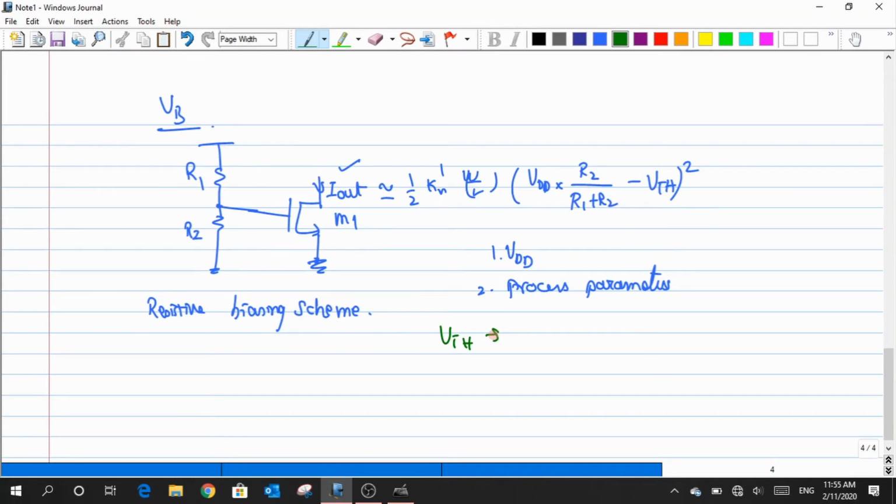Say for example, I have a silicon wafer that has some sort of threshold voltage. Now if, in the same wafer, I look at a different transistor, the threshold voltage of that particular transistor would be different from what you have chosen. Clear? So the value of VT is not constant throughout the wafer itself.